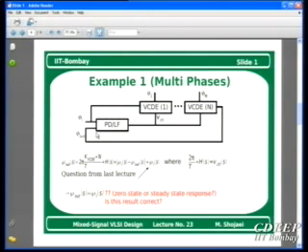Having a filter or not having a filter doesn't have any effect, because the filter doesn't sense any change in the differential phase. There is no instantaneous error generated at the input of the phase detector. There is no stimulus to the filter, therefore its output will remain constant.